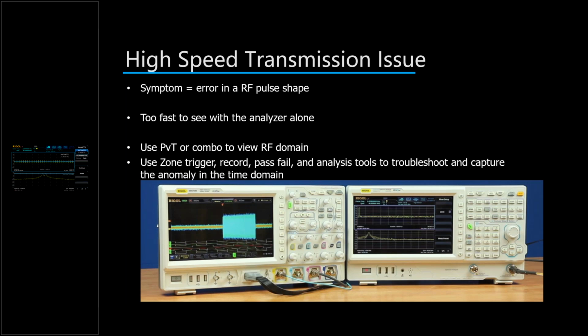If I take my sweep view down to about 5 milliseconds, there we can see it happening about once a millisecond. And now if we zoom in as much as we can, down to 100 microseconds, you can see just on the left side a very short duration pulse. That pulse is less than 2 microseconds long, well below the POI of this instrument, but we're able to capture it consistently. But we're still having trouble finding what's wrong with this signal, or what's happening occasionally that's making it concerning.